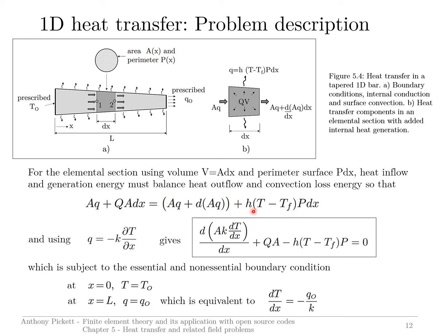This is the heat transfer coefficient for the surface, and this is the difference in temperature between the surface temperature and the environment temperature shown here. P is the perimeter, A is the sectional area of this. We use our usual flow equals negative of conduction and the temperature gradient, which is plugged into this term here. And after simplifying, you end up with this energy equation here.